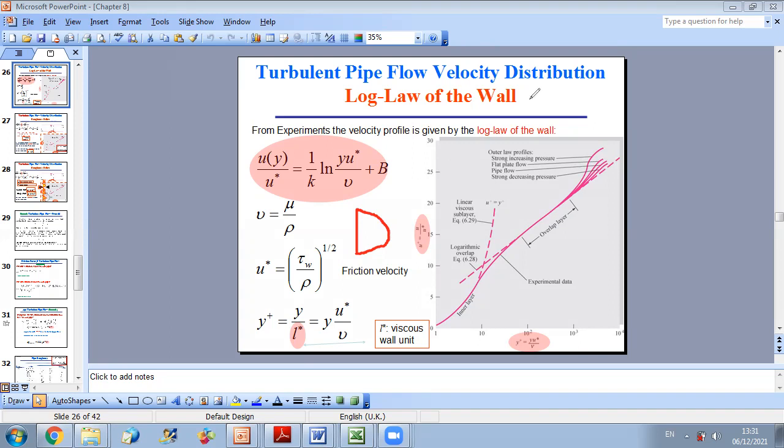This is why we do experiments. So we say, for example, I have a duct and I want to find how the profile of velocity is. I expect that it will be closer to the flat profile as Reynolds increases because the viscous effect will be reduced. So what we can do then is to say my purpose is to find u as a function of y in the case of turbulent flow.